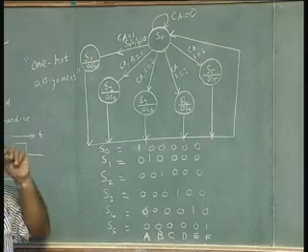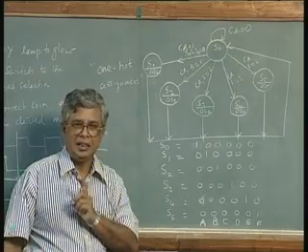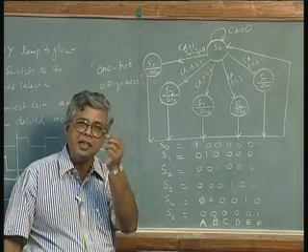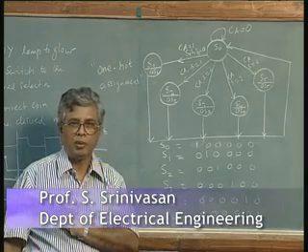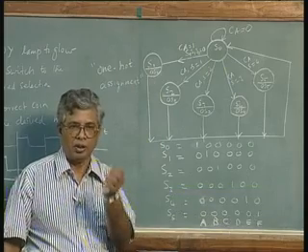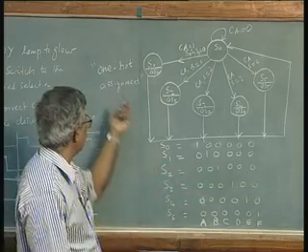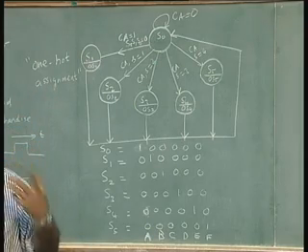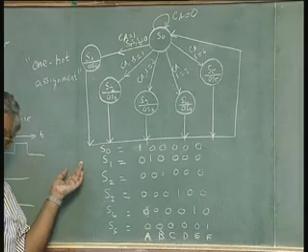This assignment of one flip-flop per state, as against the number of flip-flops decided by the number of states in a logarithmic fashion, for example, for 8 states you need 3 flip-flops, you have 8 combinations, is the normal assignment procedure. This assignment procedure gives a simpler design, and if you have more flip-flops than you need in any system, you will use this method because the design is simpler.